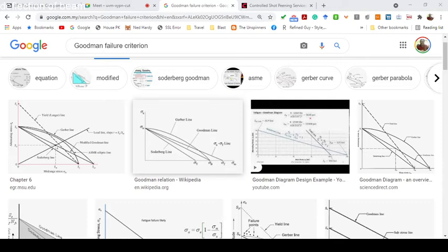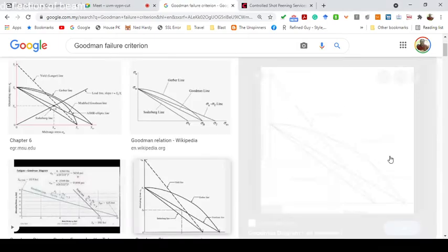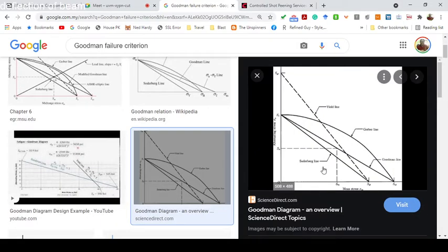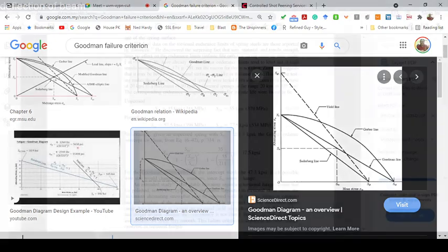Okay, you just project the line and you intercept it using the skill that you have from mathematics class. If you remember the equation y equals mx plus c, the teacher asks you to project the line like this. You project the line, then you get the value. You just have one value, let's say the mid-range value, and then you project to intercept the line, and then you get the alternating stress value. Okay, this is what we mean by intercept.